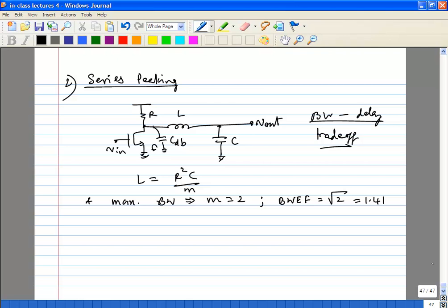Not necessarily. What you'll have to see is how much series resistance there is. You'll have to work out the details of the impedance. It won't be as important as what we have seen before for VCOs, for example. But it may be important. Eventually, after a certain point, it will become important.